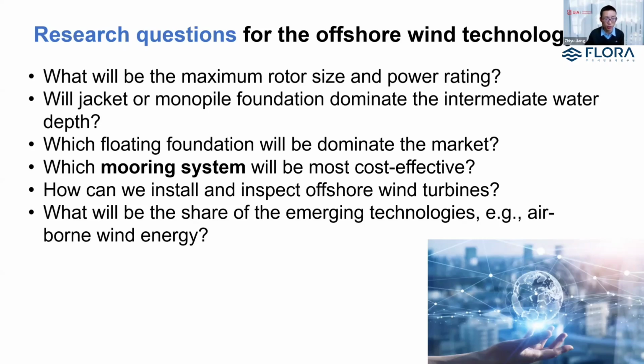So this is also related to the third question that I mentioned here. But this question concerns the floating foundation, right? We know that spar foundations are very good for rough environmental conditions, typical of the North Sea. And semi-submersibles are very good for installation and maintenance because of their shallow draft. They can be easily towed, installed and maintained at a low cost. But which floating foundation will eventually occupy the market? This may very well depend on the site location, the country, or sometimes political preference.